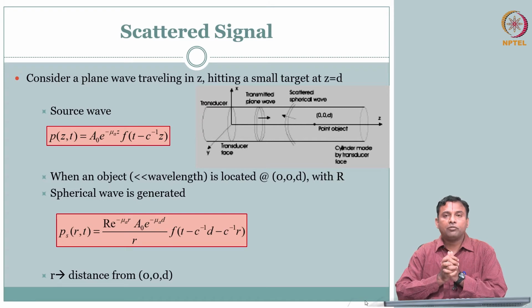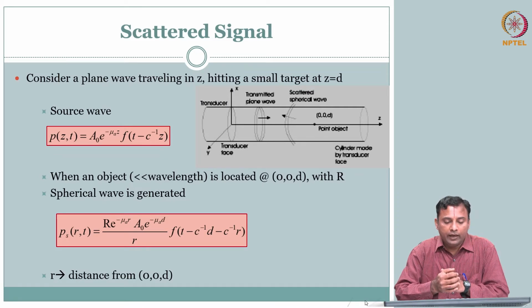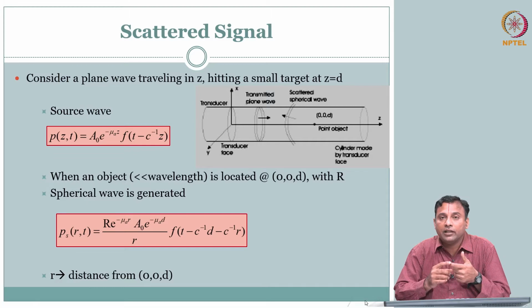Okay, so after understanding the ultrasound wave equation, we reduced 3 dimensions to essentially a 1D propagation, and in that we talked about the interaction of this wave with the material medium. Namely, the important interactions that we captured were reflection coefficient, transmission coefficient, angle of incidence, angle of reflection.